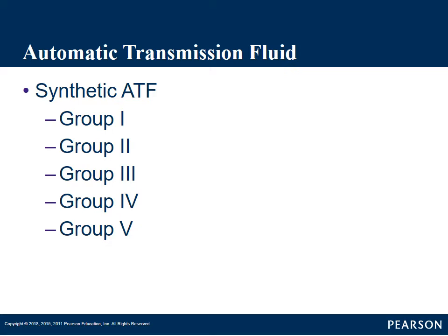They come out, the manufacturer says, we filled that transmission up, you never have to service that transmission. I personally don't believe in that. If it's got a drain and a refill procedure, let's put it on a maintenance schedule. And we'll talk about that in more depth when we get into servicing automatic transmission fluids.